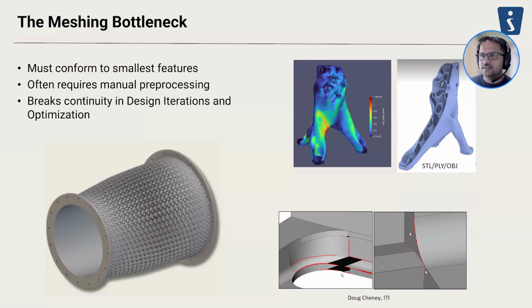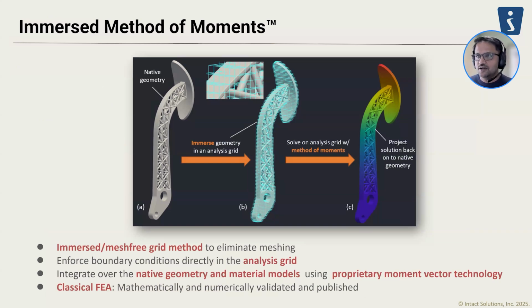So to address that challenge, we have developed a meshless, mesh-free simulation technology using the immersed method of moments. The key difference with traditional mesh-based technology is that instead of trying to mesh the original part, capturing all the details and geometries while meshing, we immerse it into a grid of finite elements. And during runtime, we deal with the cells where the geometry intersects. We deal with all the computations at runtime instead of trying to mesh at the very beginning.